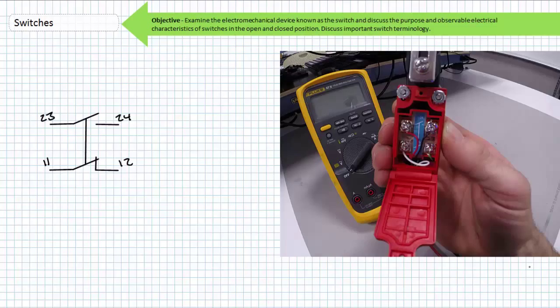If IEC isn't your thing, you can always look it up on the internet, or just kind of guess what the schematic is saying. There is a vertical bar between the lower and upper switch. My guess is that this is the mechanical interlock. When the actuator arm is tilted, this should actuate both switches from their deactivated state to their activated state. The bottom switch has a vertical connection between its pole and throw. The top switch is missing this modifier. My guess is that the bottom switch is the one that's normally closed in its deactivated state. The top switch, since it's missing this modifier, is probably the one that's normally open in its deactivated state.